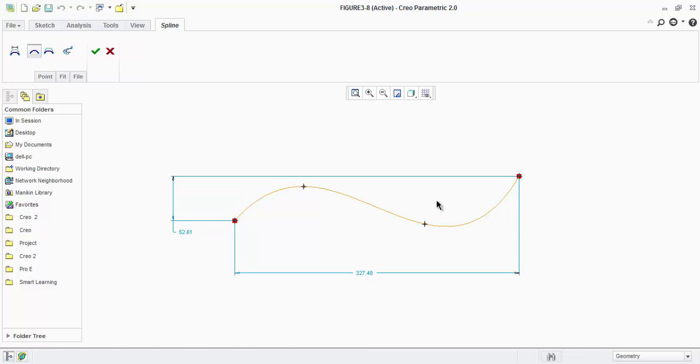And if you want to add an interpolation point, you can just select where you want to add it, right click and choose add point. You can see the interpolation point will be added at the specific point. If you want to delete any interpolation point, you can move the cursor near the interpolation point, right click and choose delete point from the context menu, and you will be able to delete it. Then if you want to still control it, you can move these interpolation points as needed.